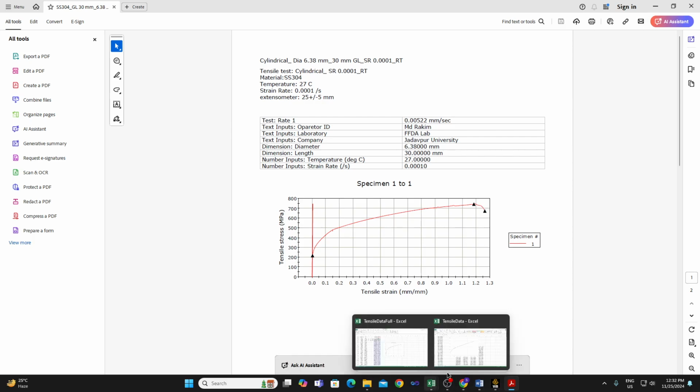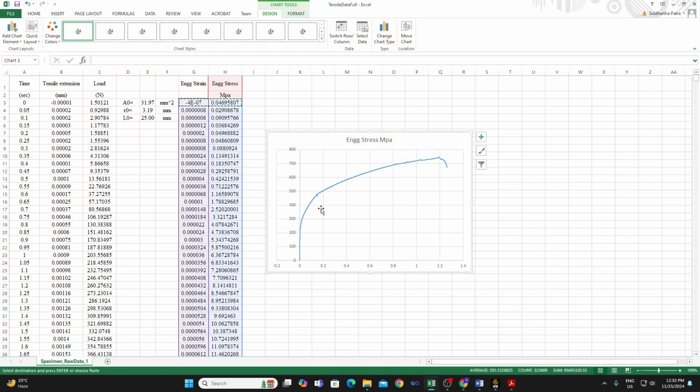The one thing to note there is that once the extensometer is removed, suddenly the slope seems to change abruptly. The reason I use the word seems, because that is not exactly what is happening. Because once the extensometer is removed, once again let me repeat, the calculation of the strain is not accurate. It's actually the crosshead movement that is being fed to the additional extension. So it's not particularly scaled or anything.